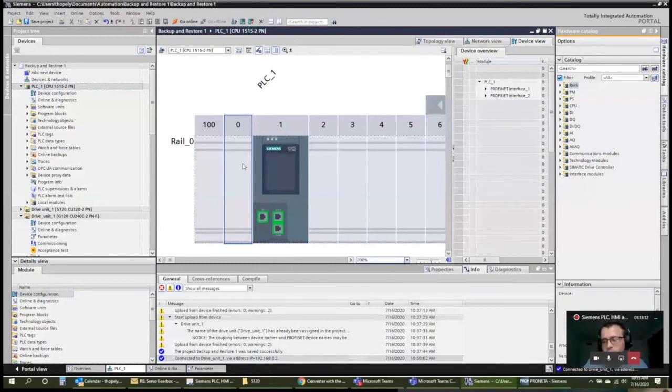The key is, just because you have an Ethernet port, whether it could be any device, doesn't mean it necessarily supports Profinet. It has to be explicitly labeled as supporting Profinet. The difference, to work off of what Terry is saying, is you typically have your 7-layer stack, and if you're using standard Ethernet comms, you have to work through every one of those layers to get your information sent to the correct place. With Profinet, it's using real-time comms, and it's only using 4 layers, I believe. I think it's 4. It goes from the physical to the data link layer, and then it skips right up to the presentation application layer. So it essentially gives you predeterministic, faster communication than standard Ethernet.